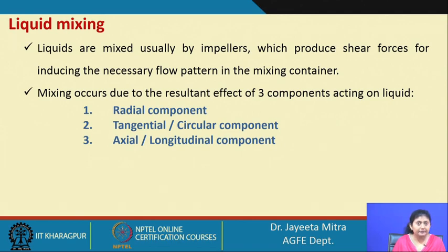Radial direction in the sense from the barrel side towards the inner side or the reverse, and tangential, that is the fluid element that is at the end of the impeller being thrown in a tangential direction, or axial, that means along the impeller shaft they are moving. So, the vertical mixing will take place. All such phenomena, in many cases all three may happen or a combination of them. Okay.